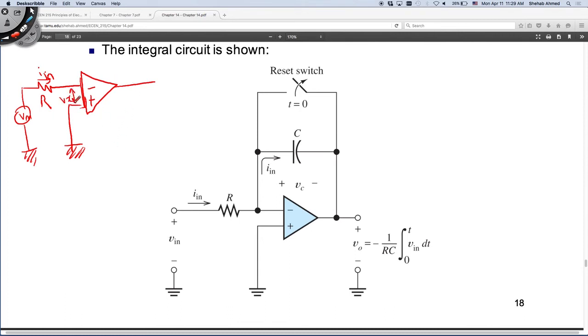Vx is here. Vx is equal to what? 0, the positive terminal voltage, minus the voltage on the negative terminal. The voltage on the negative terminal is V input, right? So 0 minus V input. So it's a negative number. What does that tell you about the open loop gain? The open loop gain will be a large negative number.